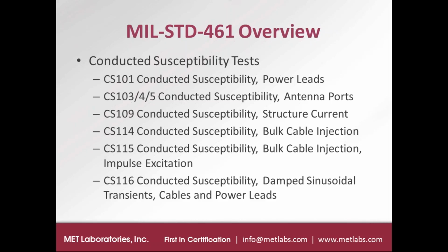So that test has a very limited applicability only to very limited type of devices, but it would represent any noise on the chassis of the EUT as a potential disturbance. And then CS114 is the radio frequency range swept conducted susceptibility. CS115 and 116 are 2 different types of transient disturbances that can couple onto external EUT cables and make their way into the EUT and disturb its operation or cause damage.